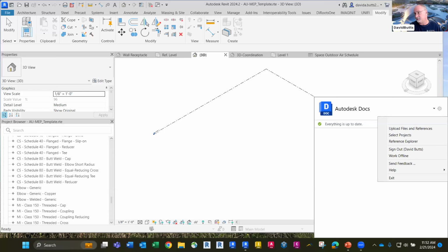Then if I'm going to have different plans, my details, whatever, that I'm keeping in that one drawing, I have that set up in my template, but the page setups are the critical part. You want to have those defined and assigned to your layout tabs. Then you just create a sheet list by saying, give me just these tabs, don't include model space. You pick them all up, get your sheet list done, save it, and you're off to the races. And I XREF my title blocks in too. I link detail reference numbers within SSM to my plan views.